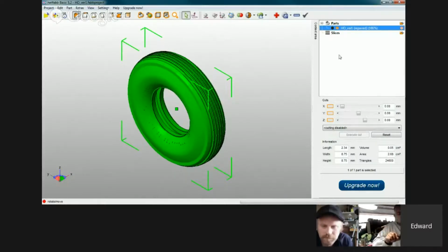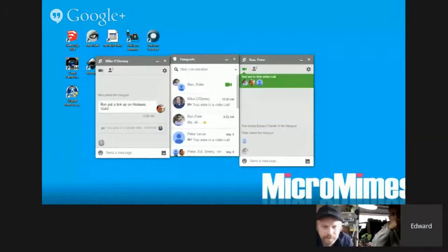Oh, good. And what we would do is I go back into MeshLab, I go to that layer screen, and I duplicate the layers. And I move the copy to one side, up, down, left, right, make it as many as I want, flatten the layers, 10 tires, 20 tires, 100 tires, make that one mesh, and I upload that to Shapeways. So now what we're going to do is upload that tire.